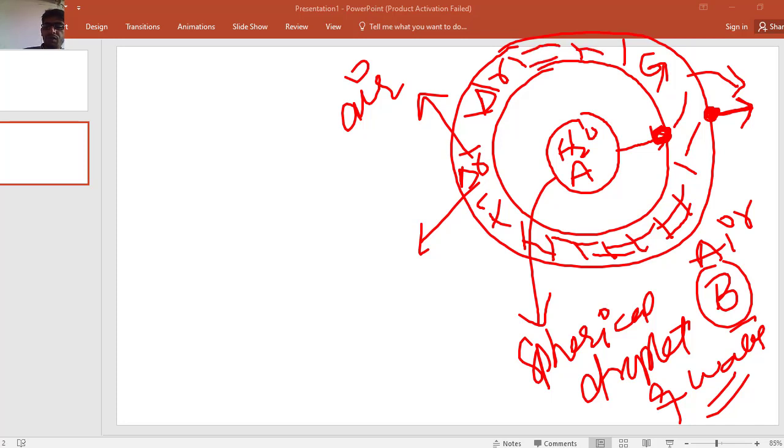There is no consumption of water molecules inside this stationary layer, and no accumulation of water molecules in this layer. Simply the water molecule will evaporate, come to the stationary layer, diffuse into it, and then come out from the stationary layer around the water droplet.